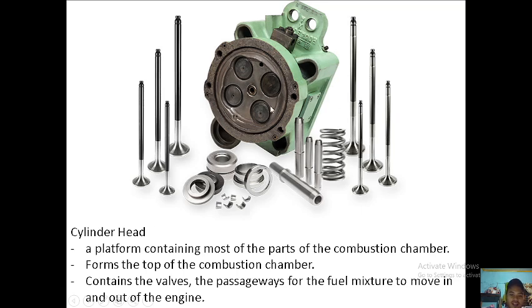Okay, this is for a 4-stroke engine. This is the cylinder head of the 4-stroke engine. We have 2 intake valves and 2 exhaust valves with a fuel injector in here, and here we can put something for starting air or for the test cock. So this is for the exhaust.